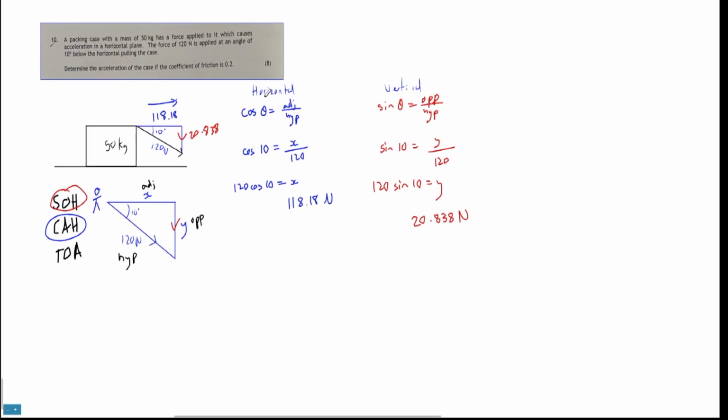Let me move this off to the side. Okay. So let's get another color for friction. Friction is fun. So F_fric is equal to mu N, where F is the friction force created. It's going to be resisting our motion. And then mu is the coefficient of friction, and N is the normal force, the upwards reaction force.